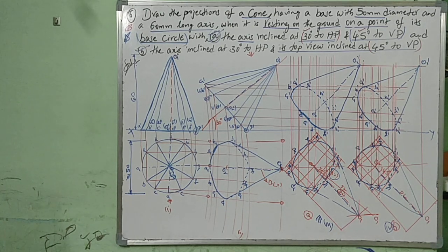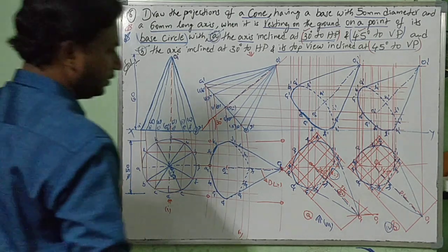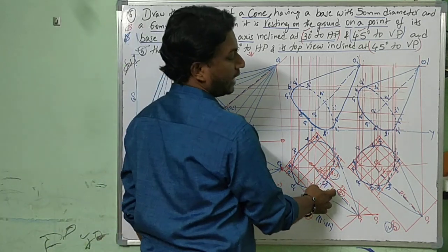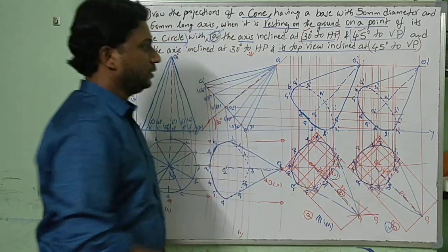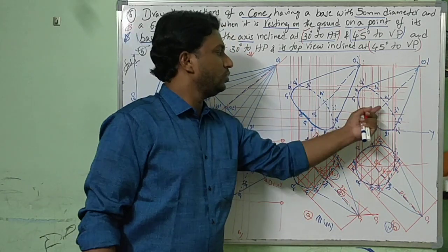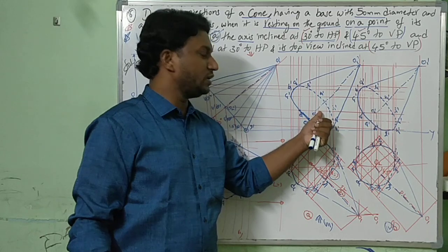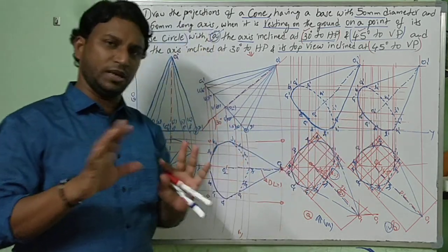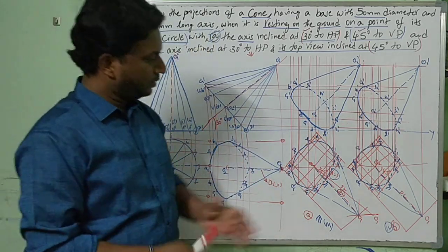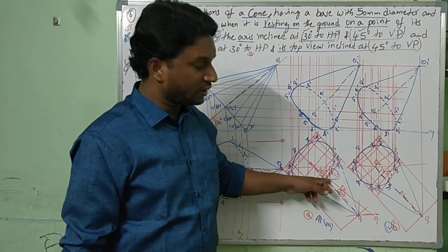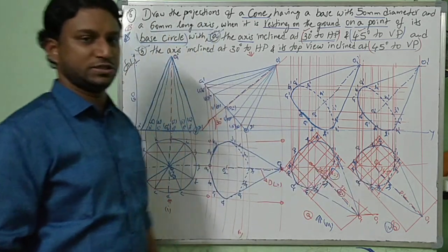You may get a doubt, sir, what difference have we achieved by solving this problem? Nothing. Here we have found beta apparent, we have done directly. These two views, the third stage front view and the fourth stage front view, will look similar. But here they are different. Here it will become the beta angle, here it will become 45 degrees.